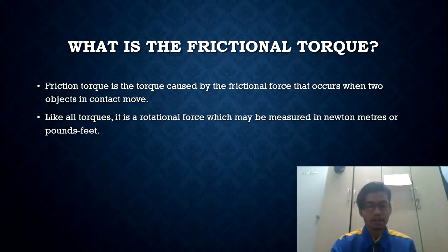And keep in mind, the static friction will be different than when the motor is in motion. And finally, we don't calculate it. We measure it. It is purely a mechanical effect, depending on things like bearing quality and aerodynamic effect. In general, motor frictional losses are ignored. If we have to take them into account, we are working too close to the edge.